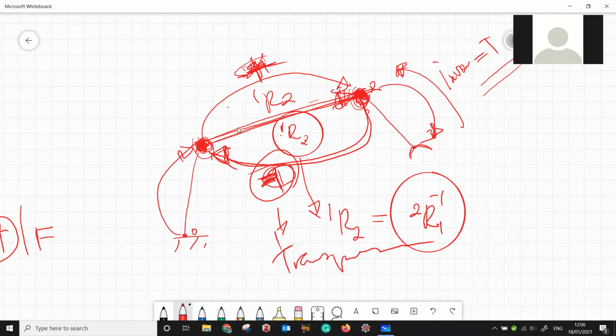If you are coming forward, then you can go in reverse by the inverse, but for a rotation matrix the inverse is equal to its transpose. That means inverting a matrix is difficult, right? It's computationally difficult. So if you have a rotation matrix, why do you do an inverse computation of a 3 by 3 matrix? It's difficult, right? So instead of doing the inverse, you can simply take the transpose. Just exchange the vertical and the horizontal elements, and then you get the transpose within 5 seconds.